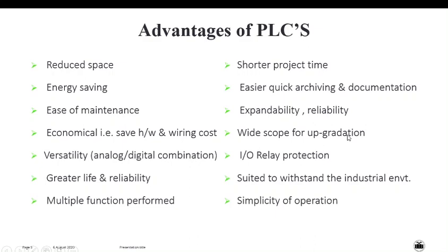So if we have purchased a PLC with 4 input 4 output, and if my business is growing, so I thought to expand my business, but it will require 8 input and 8 output. Okay, so in this case I have to change the PLC. So this is one case.